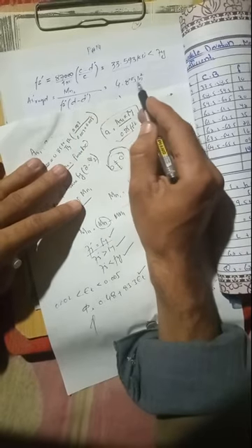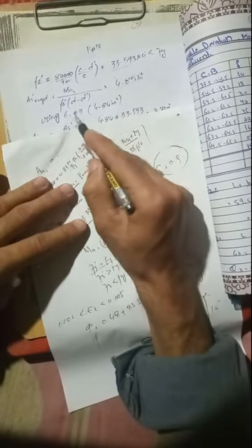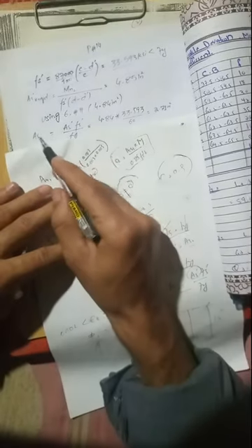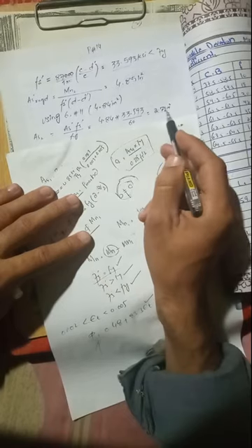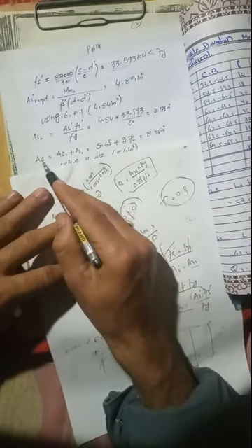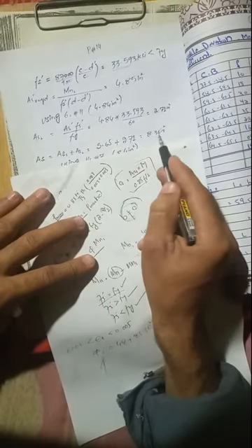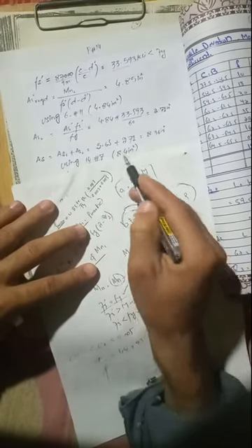Okay, so 4.85 square inches. Again, we need a bar arrangement: for this bar, we provide 6 number 11 bars, 4.84 square inches. Now As2, which is the actual reinforcement, As2 prime times Fs prime divided by Fy, is 2.71 square inches, right? Now we need As. As1 is already calculated, As2 is this one. For this reinforcement, we have to choose 14 number 7 bars, right?